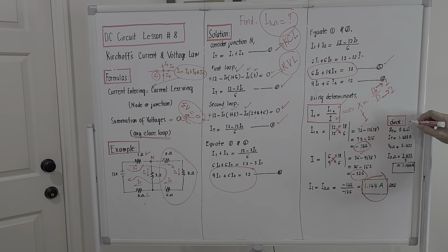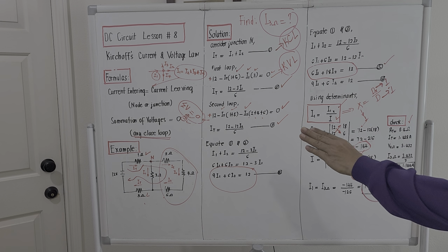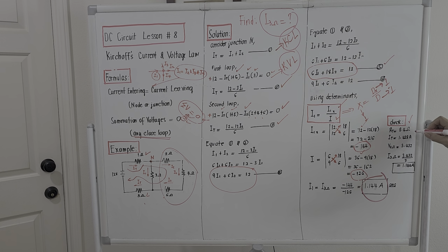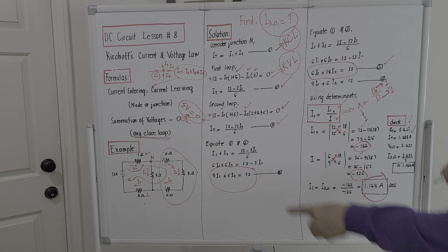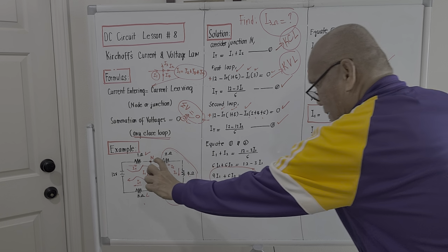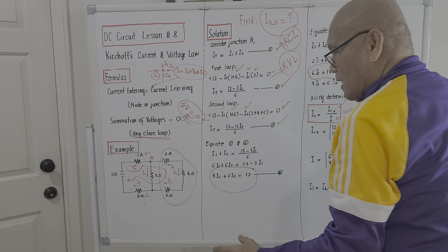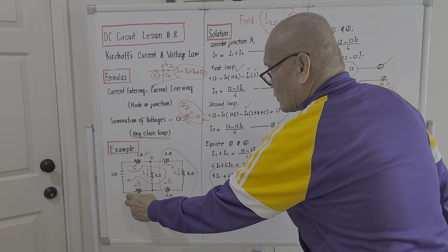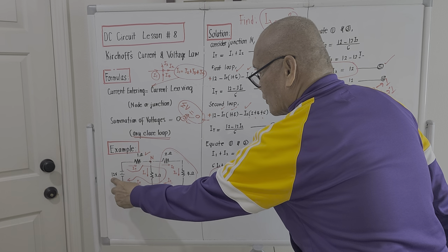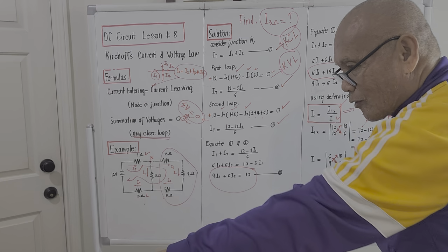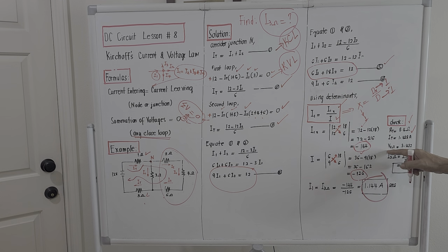Our total will be 8.4 ohms. So if we try to compute for the total current emanating from the 12 volt source, it will be 1.428 amperes. It will be 12 volts divided by this. And to compute for the current passing here, we will be subtracting the voltage drop here minus the voltage drop here from that 12 volts, and that will be the voltage across the 3 ohm load. As per my computation on my notes, the voltage across the 3 ohm load is 3.432.